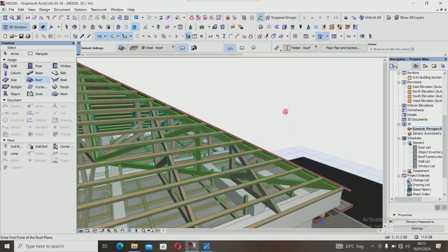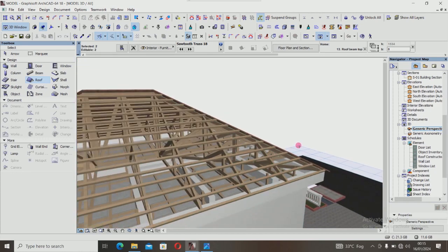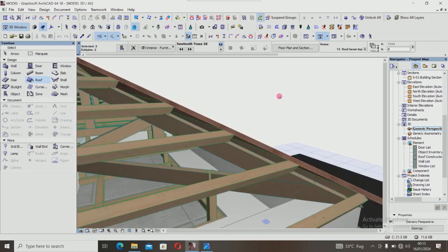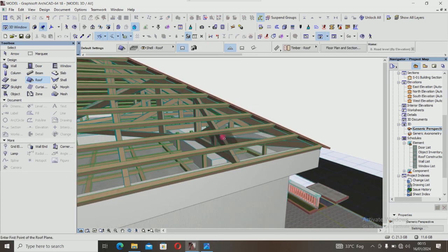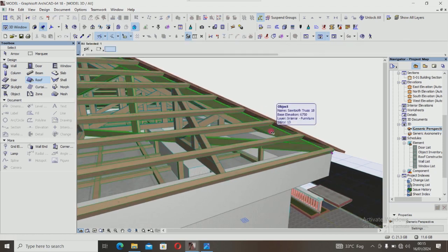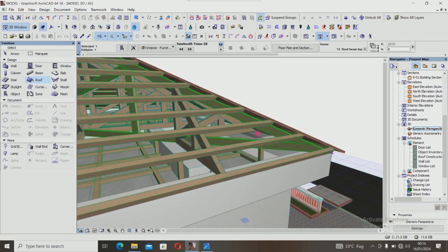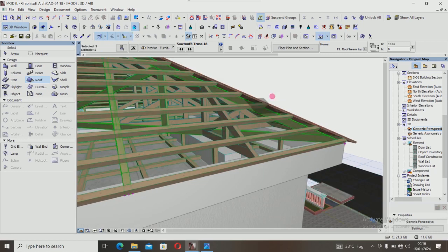You get that? Now, when designing a roof in Archicad, the normal slope they ask for is the slope that flows with the side of the roof, not the edge. But in this program, the two angles of these rafters are very, very important. Before modeling a roof, the normal angle of the roof, or the roof slope, flows with this rafter, so you have to take note of it. To get the angle of this edge rafter, you have to do a little arithmetic. That is what I want to show you: the relationship between the angle of this rafter and the angle of this edge.